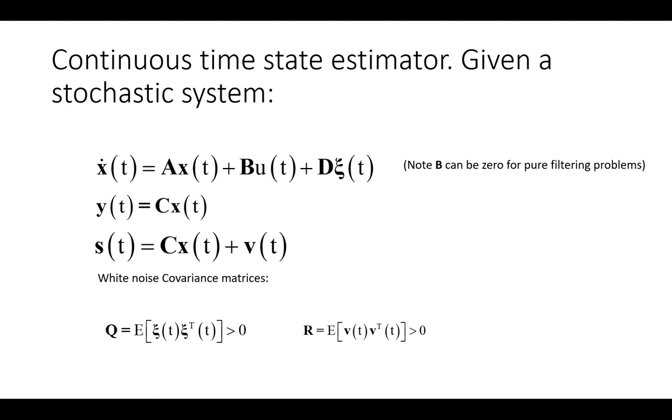It's a system driven by white noise, and it's a little bit abstract at the moment, but we can take any transfer function and convert it into this, usually without this part here. It's not ζ, it's ψ, the Greek letter here. Normally x dot equals Ax plus Bu, y equals Cx, but we've got the additive noise at the input, which is called the process noise, and additive noise at the output called the measurement noise.